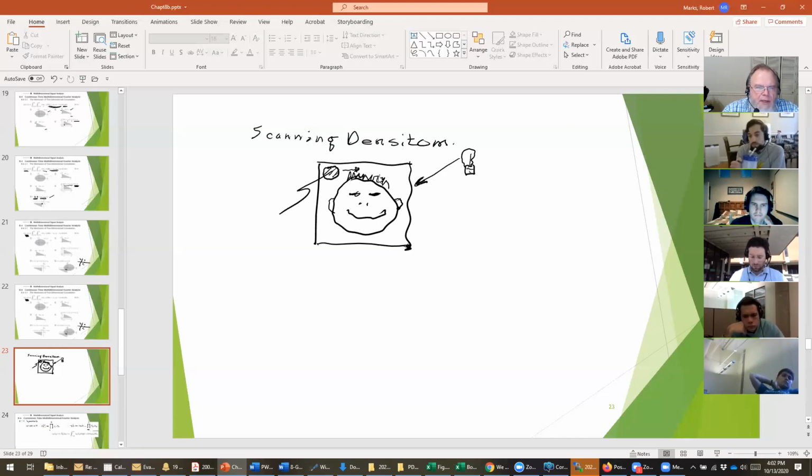So if you were over here, for example, with the photo detector, what would you get? Well, you would get whatever the gray level was for all of the values within the photo detector. Does that make sense? And you would move this photo detector around almost like a raster, and you would capture the two-dimensional readings from the photo detector in order to try to capture the image. The problem is that the photo detector is too large to catch a lot of the detail, right? That photo detector is big with respect to some of the detail that is in the image.